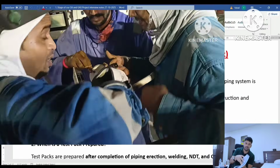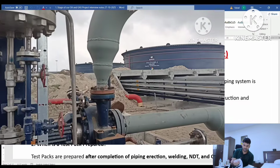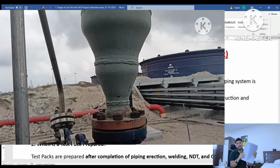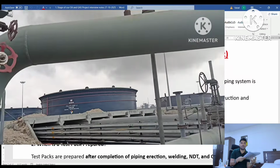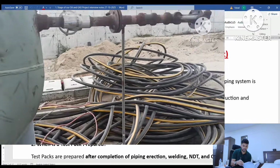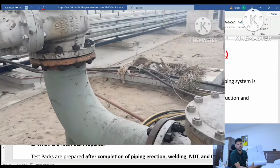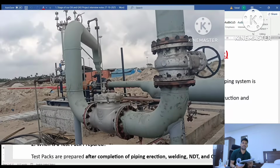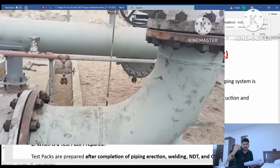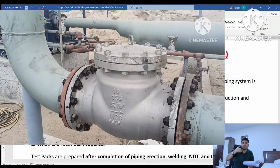This test pack contains all the documents related to our piping system. For this piping system you have to prepare one file like this. After preparing this file, all the lines are checked according to this file, according to the markup you have already made in the P&ID. On behalf of this markup you have to go and check with the client, in detail, that all the construction activity is done, all the inspections are recorded, all the testing work is completed.